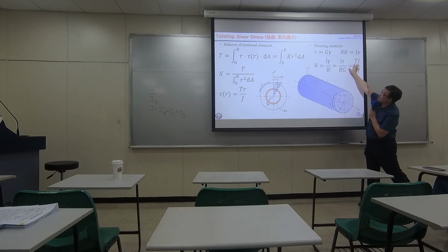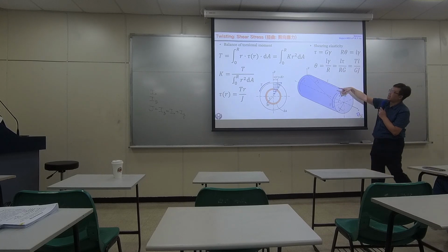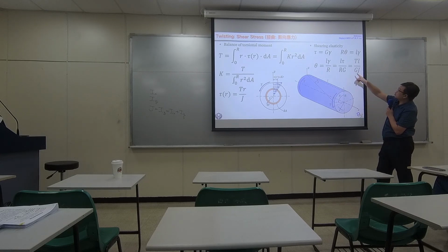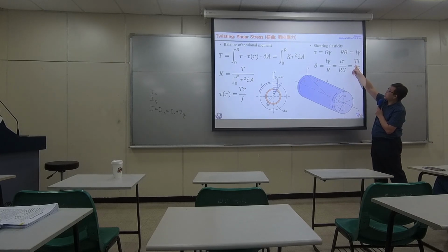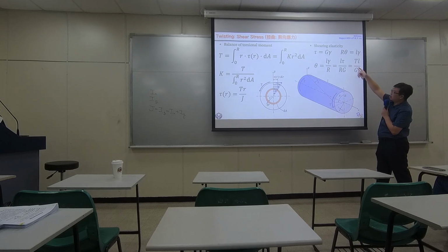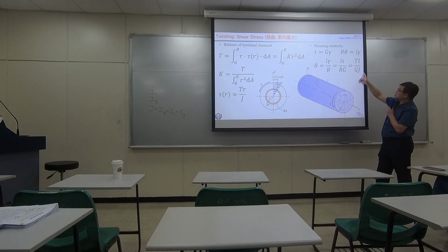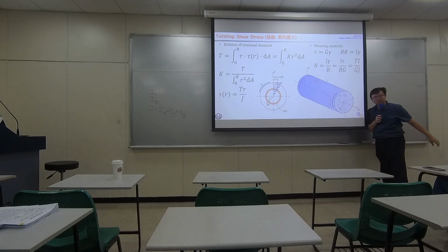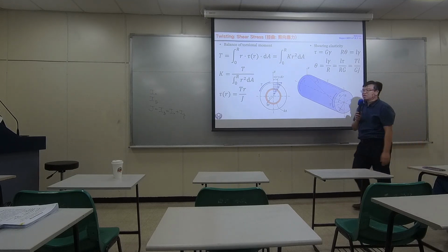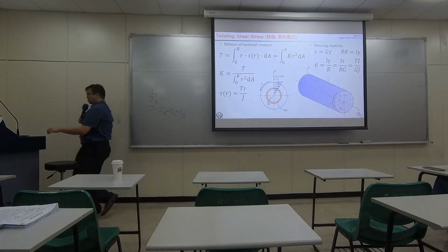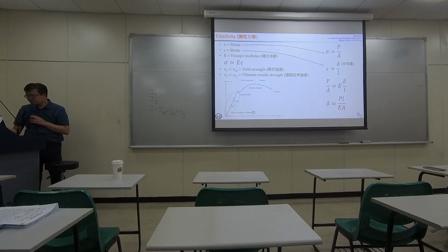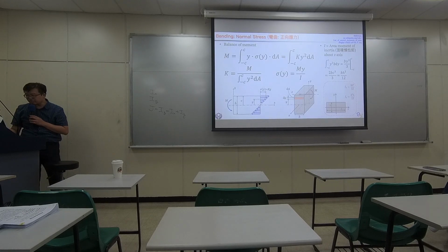When we have this, we can put everything together. Then we end up with the angular deformation, how much you twist, equals how much torque you apply to the material. L is the geometrical information. G is the material property. J is a parameter about the cross-section area. So similar to normal stress analysis. Earlier we have, which equation?